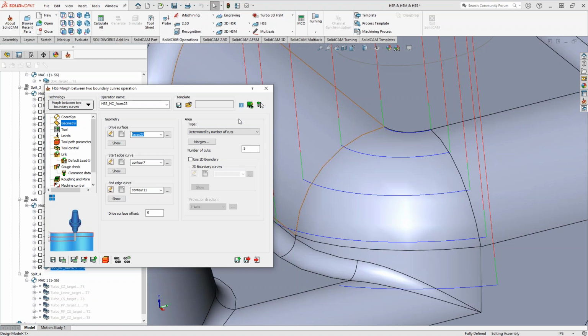If you're trying to only do, let's say, maybe a slice down the middle, or like I said, with swarf machining, I would tell it to use the side of the tool and a 5-axis toolpath but not do any steps. Just go right down to the bottom of the surface and then just do one pass, maybe doing a final finishing pass or something like that. So this is just another way to further control it.